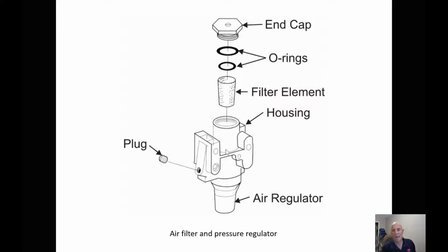If we ever have to clean the filter, we can remove the cap, the 2 O-rings, remove the filter, and wash it out. Now if it gets plugged with oil, we're getting oil from somewhere and we need to find out why, because it'll just plug up again.